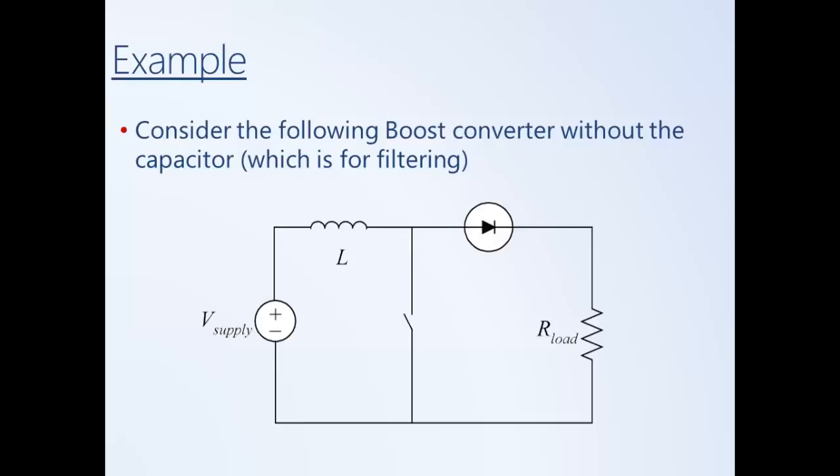If you take another class like a power electronics class, you will get into much greater detail, and you won't necessarily analyze it from first principles. In particular, there's often some sort of tricks done where you're able to basically look at the circuit in steady state and make some assumptions about how the behavior in the on state and the off state are averaged over.